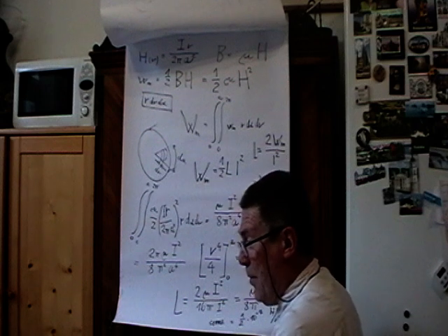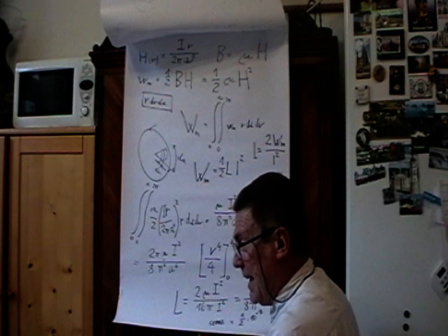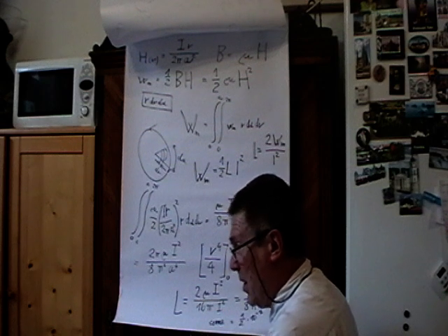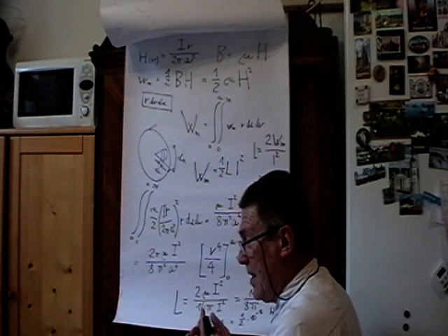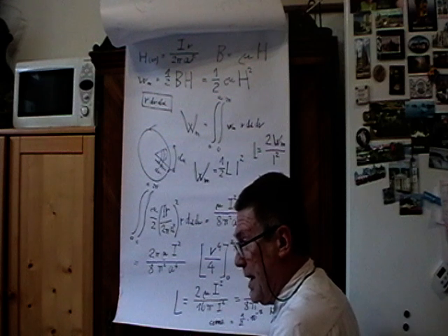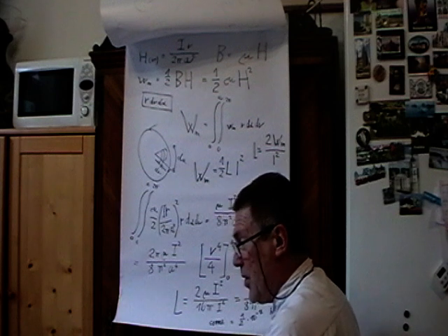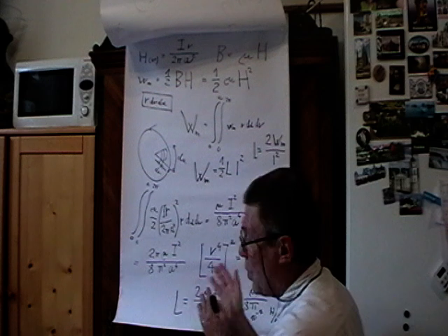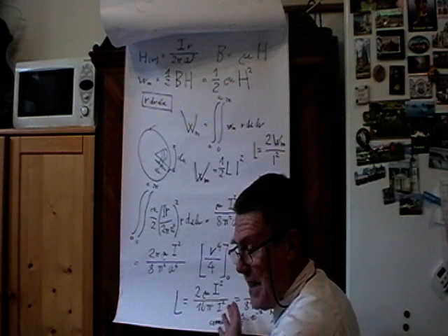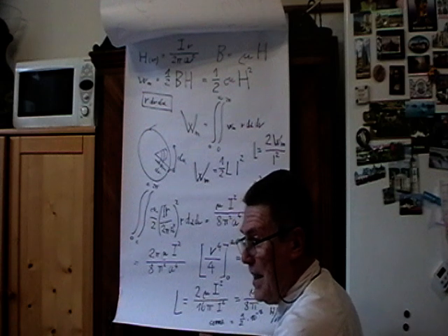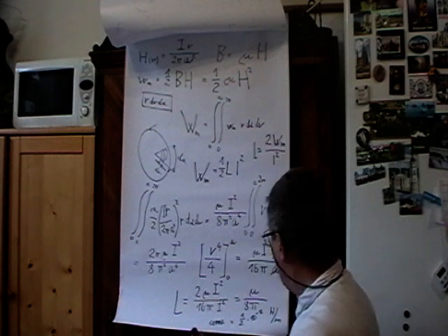We have found that calculating internal inductance is barely possible with the static definition of the inductance, and we had to use the energetic definition, which we found suitable for the calculation. We have calculated one simple case of a circular conductor and its inductance per meter.